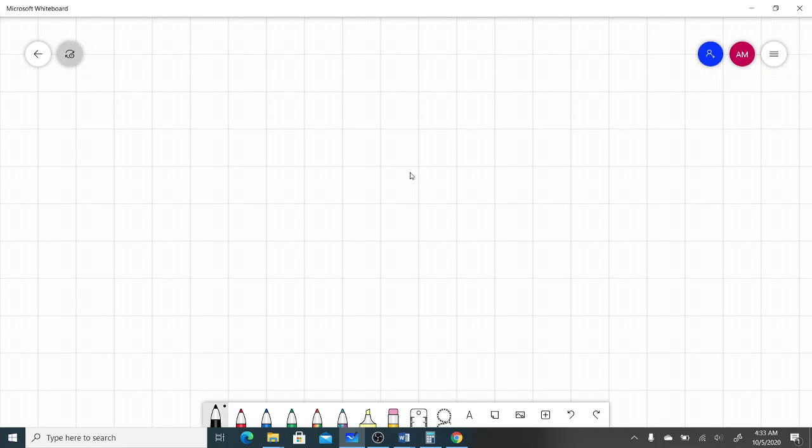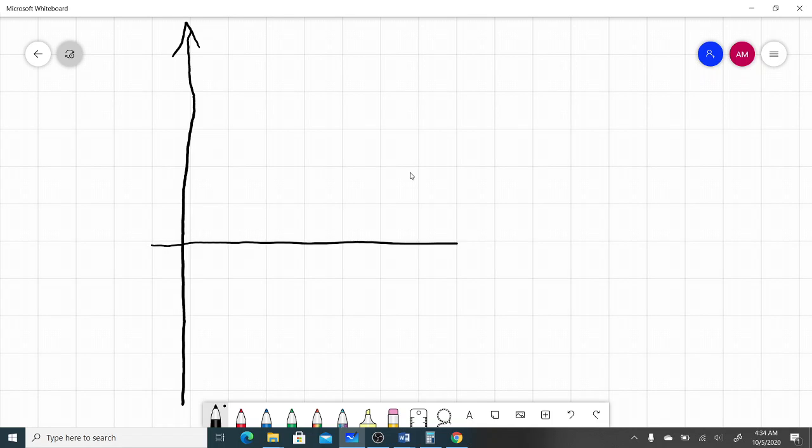When we draw a time-space diagram, it's an XY curve. On the y-axis, this will be our distance, and on the x-axis, this will be the time. And you guys draw it to scale. I'm trying to put it on my computer, but it's not going to be as to scale as when we do it by hand. So this is time in seconds, and this will be our length in feet, and use whatever scale you like.